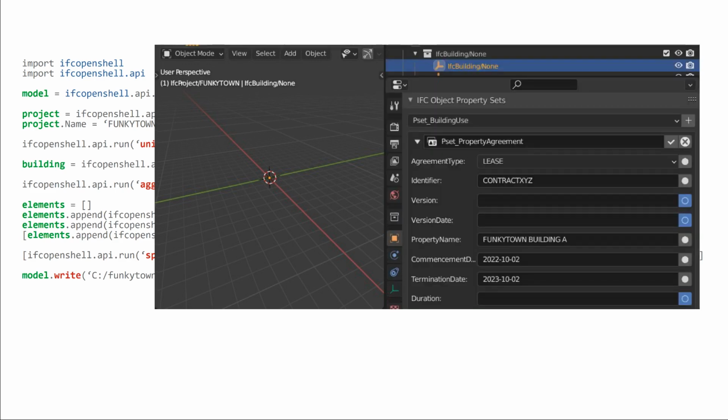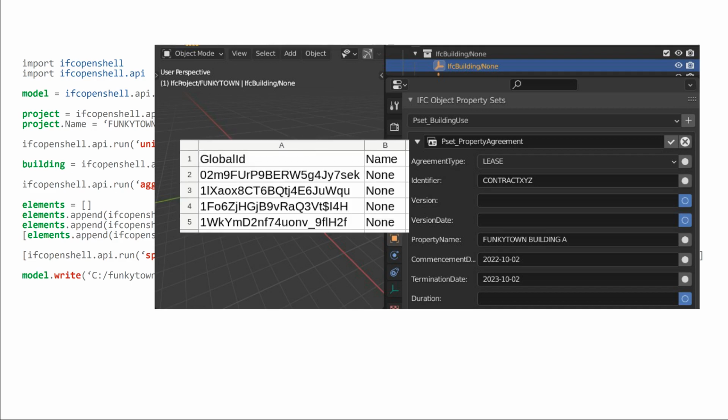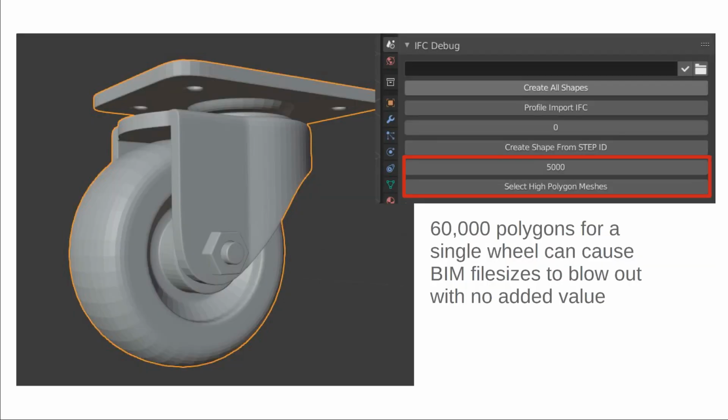And we can use other tools like the IFC CSV tool, and we can export a spreadsheet schedule of our walls. And if we want to, we can edit the spreadsheet and then re-import it back into the IFC file. And this lets us very quickly audit and edit IFC data in bulk. So you can see that we can mix code-generated BIM models, visual interfaces, as well as spreadsheet interfaces, all in native IFC and interoperate.